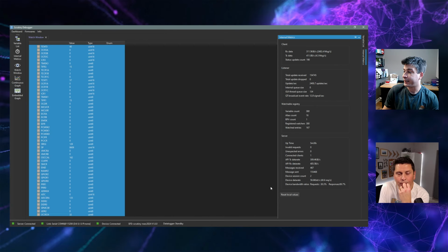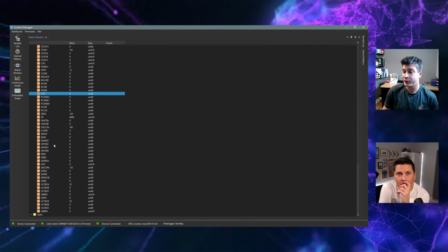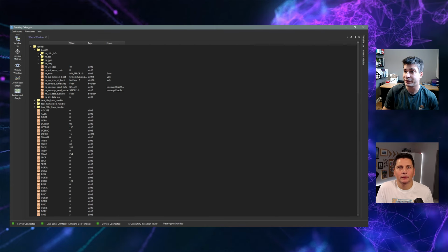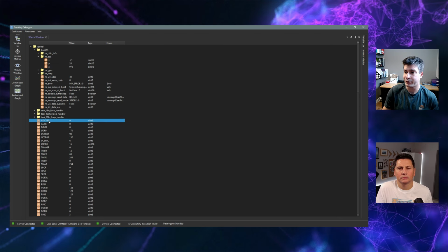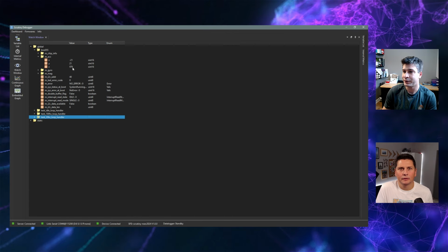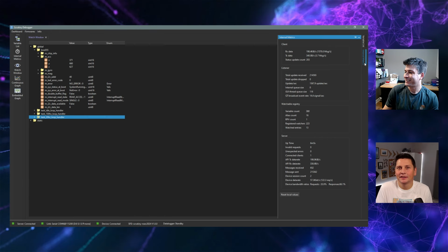And if I remove some of those, we can see that the refresh rate of the other variables will start to move faster. So this is the accelerometer value, and I'm going to remove everything below. And we should see the refresh rate start going faster. Well, it was a bit subtle, but it did. And you see, now we have much more requests per second because I'm reading contiguous memory. I need fewer requests to fulfill what I'm asking. Yeah, that makes sense.